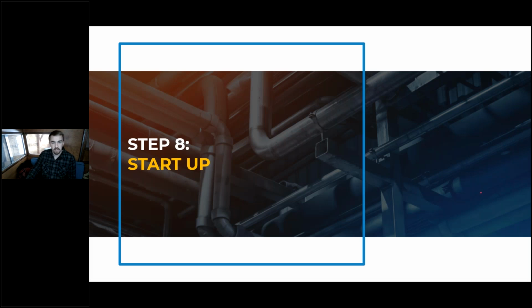So after we've installed the equipment, we can go through the startup process, right? And this is to ensure that the heat pump water heater as installed is actually going to operate efficiently and reliably. So usually the startup is done by a factory technician to confirm all the settings and make sure the heat pump's operating as expected. And oftentimes there's a commissioning agent that comes in after that to do functional testing on the entire system and make sure they're seeing what they expected as part of the design.